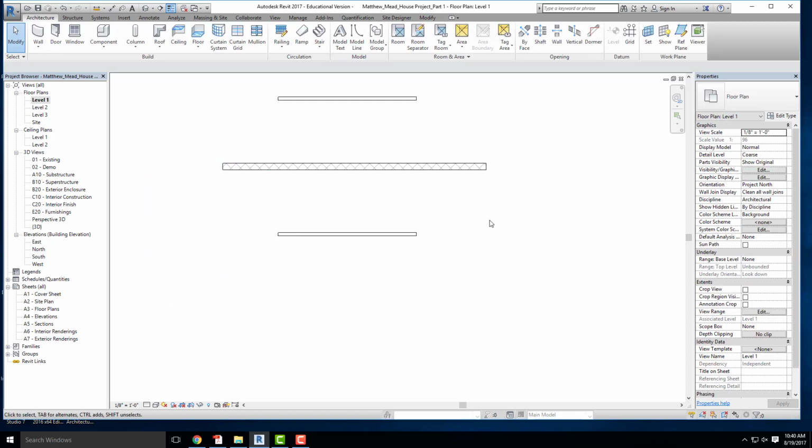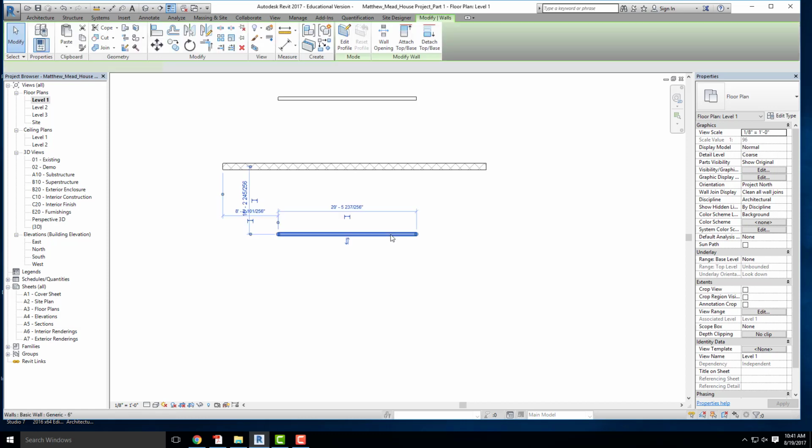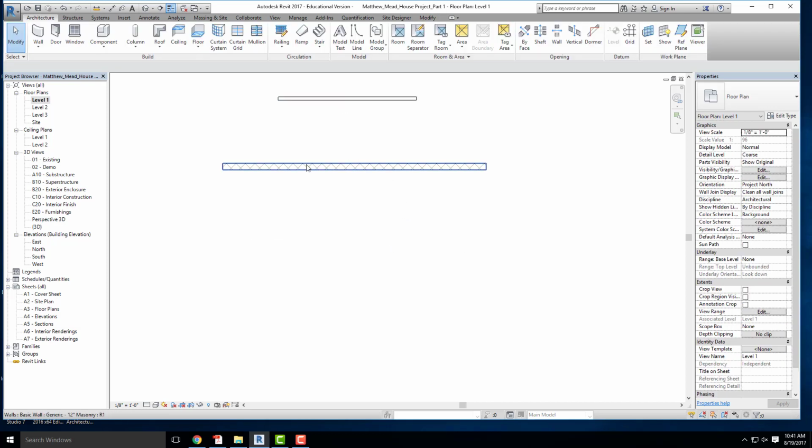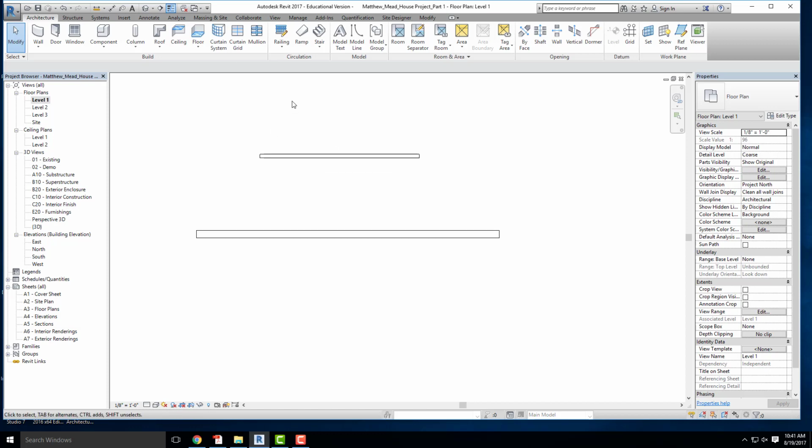Like Revit, usually there's a variety of solutions on how you can get to the end result. If I wanted to, I could copy that wall over, or I can mirror it over. You could typically get the same end result doing it 5 different ways, 10 different ways. But your goal is to figure out the quickest and best solution, so become efficient. The difference between the two is maybe you have this wall to work with, you know an axis that you want to mirror it over, but you may not have that wall. That's how you would define those two different instances.